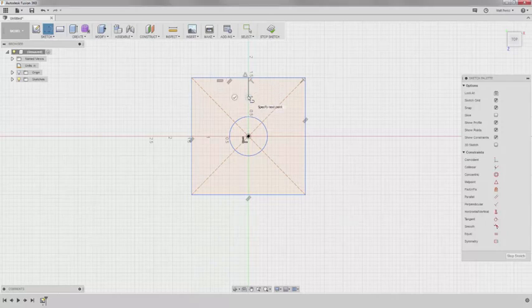This allows you to stop from adding other segments to the line. For this lesson, we want to drag the line to the right until it intersects with the construction line, making sure that it's horizontal. Next, we will click on the last point, hold down the left mouse button, and drag down and to the right.